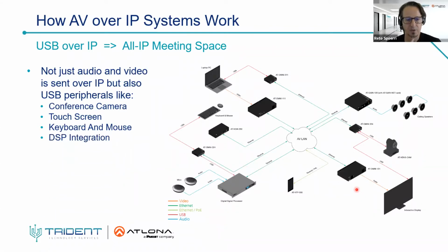Next one is a DSP integration. We already had this audio processor in the room to take care of the microphones and the speakers, but now we are adding an additional USB connection. So between the audio DSP and this peripheral, there is now a USB connection. The audio DSP also ends up at the laptop as a simple speakerphone. So no driver installation needed. It will work with PC, with Mac, with any kind of operating system. Simply connect the USB here, and your laptop will see a speakerphone, but it's not a physical speakerphone.